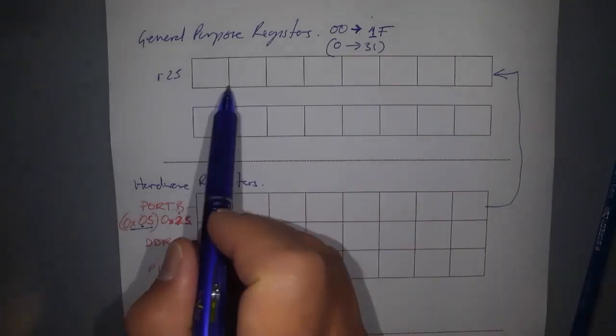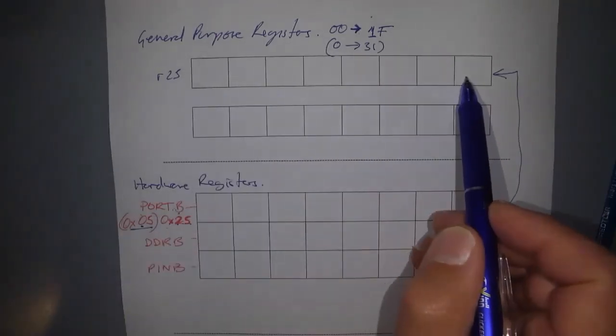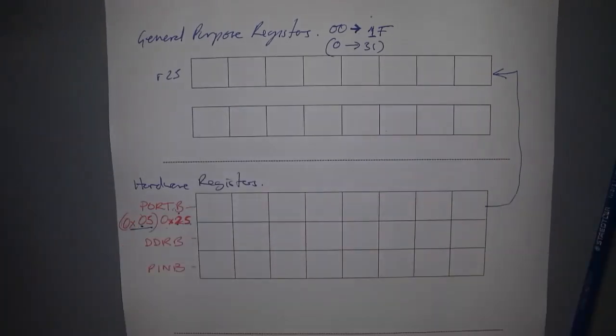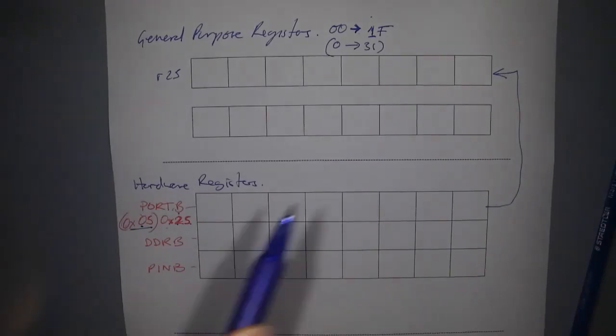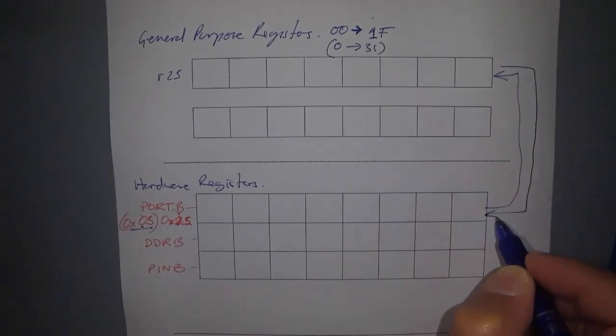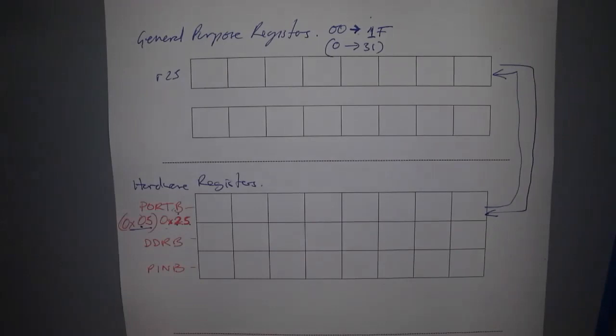And so whatever we copied from port B, we've ANDed with our masking number here. And then in the next command we take what's in R25 and write it back out again. So over here in our assembled code, you can see that.